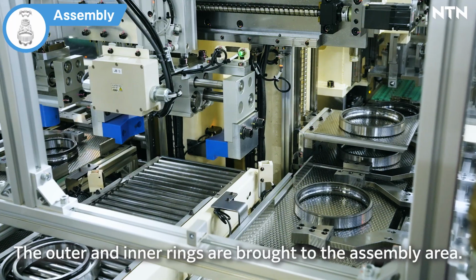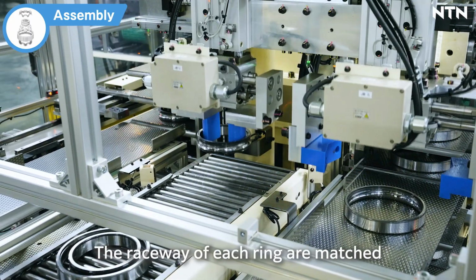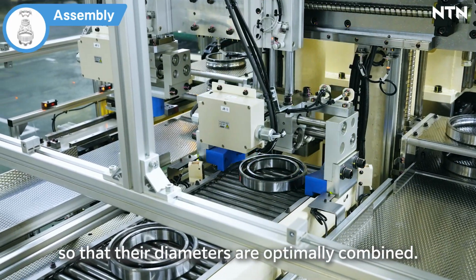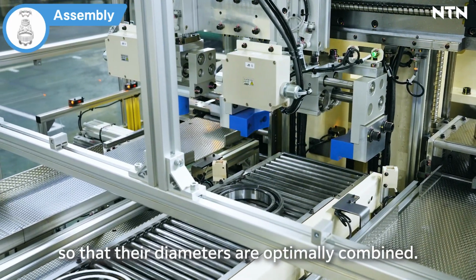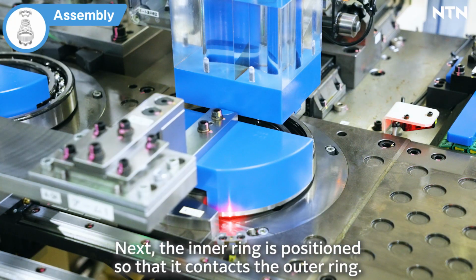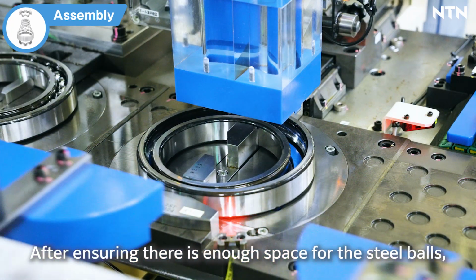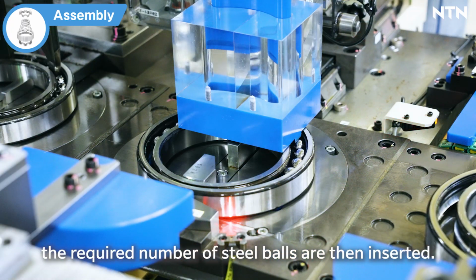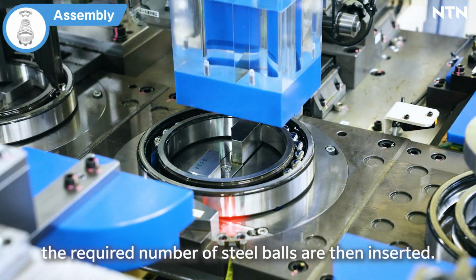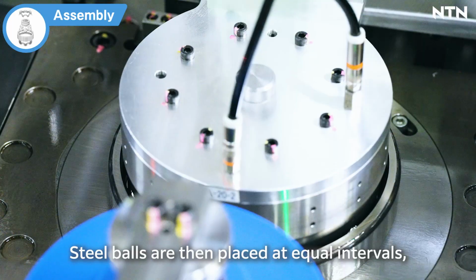The outer and inner rings are brought to the assembly area. The raceway of each ring is matched so that their diameters are optimally combined. Next, the inner ring is positioned so that it contacts the outer ring. After ensuring there is enough space for the steel balls, the required number of steel balls are then inserted. Steel balls are then placed at equal intervals.